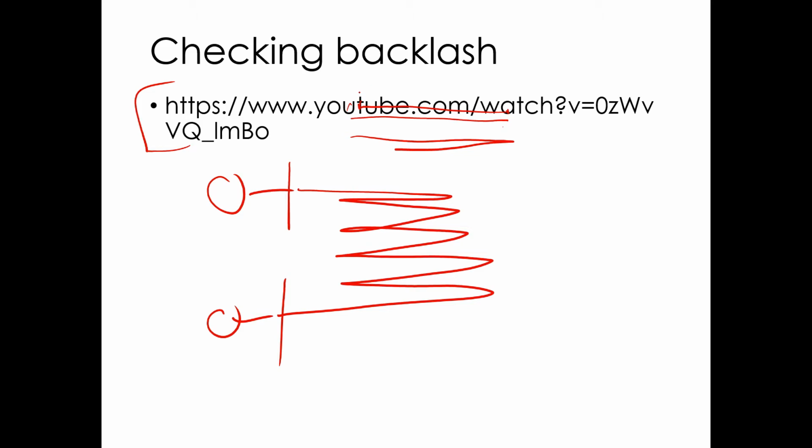start feeding it and I undo this backlash, and then I move back to here, and then I come back here, and then I undo the backlash. The end result is if I do multiple cycles, the error doesn't accumulate. It just happens one cycle and then it unhappens the next cycle. So it only happens on reversals, and if you reverse twice, the effect goes away. So it's not an error that accumulates, which is great. It means if I measure the backlash, program it into my controller, and compensate for that in my motion, I don't lose any accuracy due to backlash as long as I measure it and account for it.